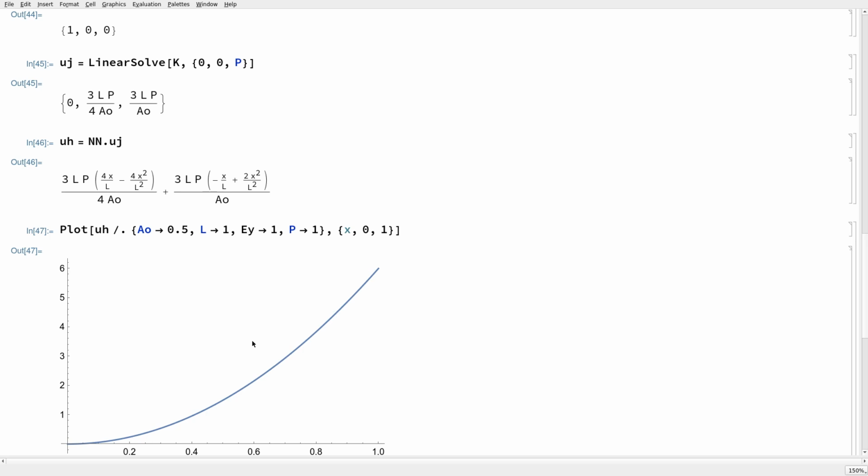Same force. Think about what the stress is. If you have a conic section, the stress is increasing as you go across toward the end because you have a uniform force at the end, P, divided by area. So the stress is getting higher as you go towards the end. Therefore, the displacement should go up as you go towards the end.